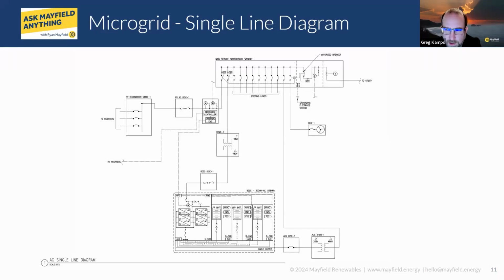And Brian, I don't know if we want to get into why an isolation transformer, or why not. It's kind of a big topic, a long topic. The short answer is that some of the energy storage systems can produce a voltage that can damage electronics, so that needs to be filtered out before it gets to the electric grid. That's why these isolation transformers are there.